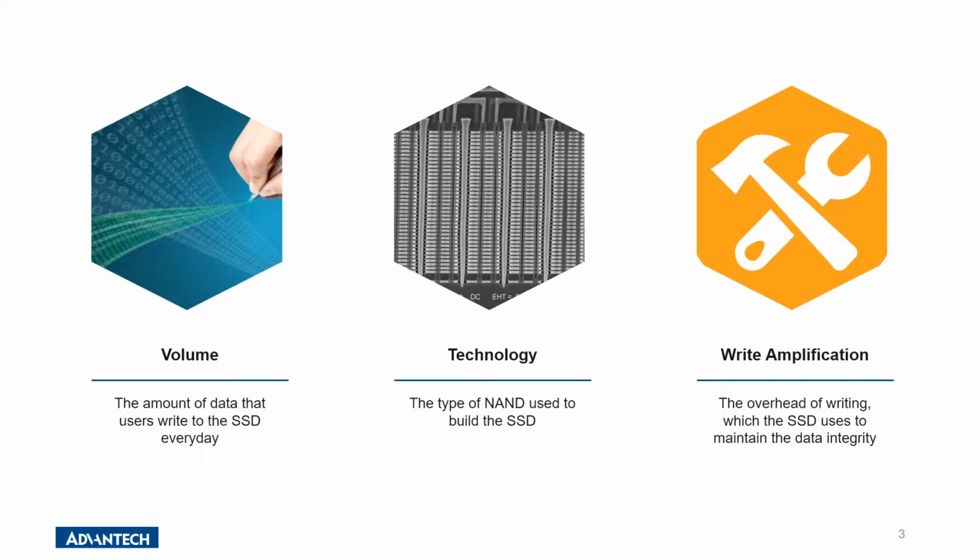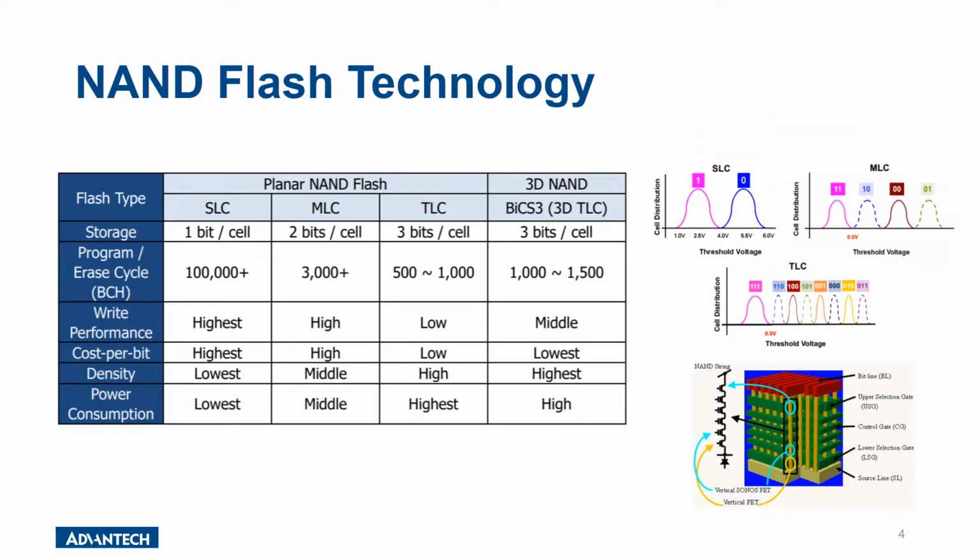The SSD's controller, for instance, will shift data around in cells from time to time to maintain the wear leveling on the SSD. This is to prevent the same cells from wearing out over time from overusage on one block, basically. We offer a wide variety of NAND flash such as SLC, MLC, Ultra MLC, and even 3D NAND that can provide a range of potential life cycles to fit our customers' needs.